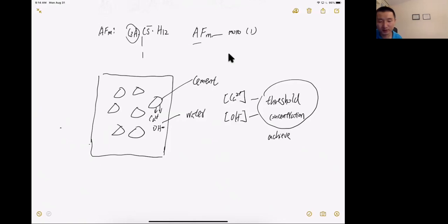When stage 3 starts, the hydration will accelerate. We have more and more hydration product produced. Okay, so when we have hydration product produced, the hydration product will precipitate on the surface of the cement grain. Okay, so remember the 3 verbs. The first is dissolve. Dissolve means the water will dissolve ions from the cement grain.